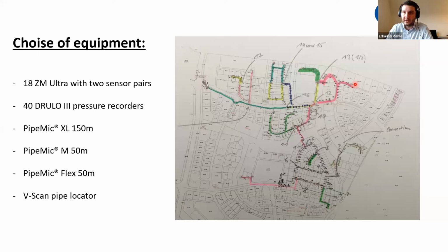I assume you can push downstream, going with the flow, but what about against the flow? Is that possible as well? Yes. That's a big advantage of this system, that with the push rod you are able to push against the flow. So at the position of insertion, you have in both directions the full length of the rod to be pushed. Okay. And the flow velocity is not that great there, about 0.5 to 1 meter per second on average. Therefore, it doesn't affect the small cable push rod inside if you push against the flow.